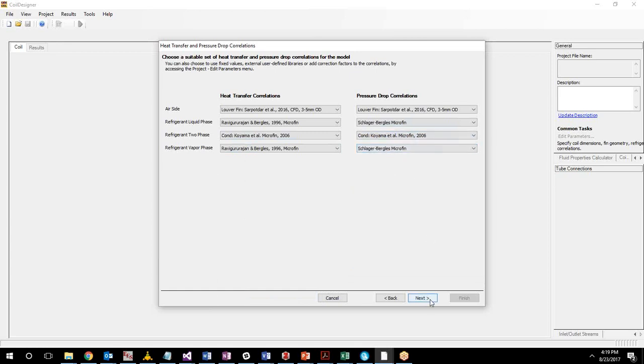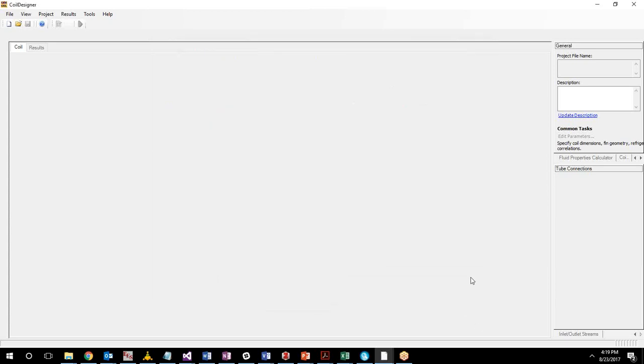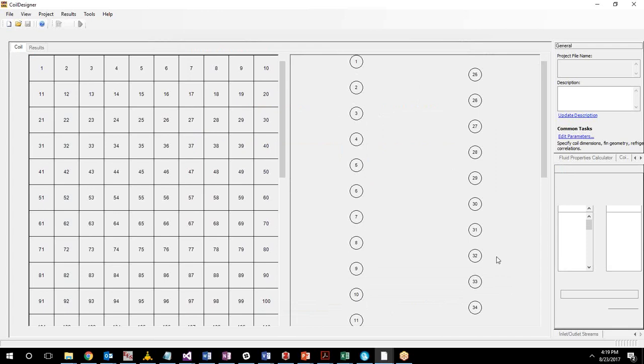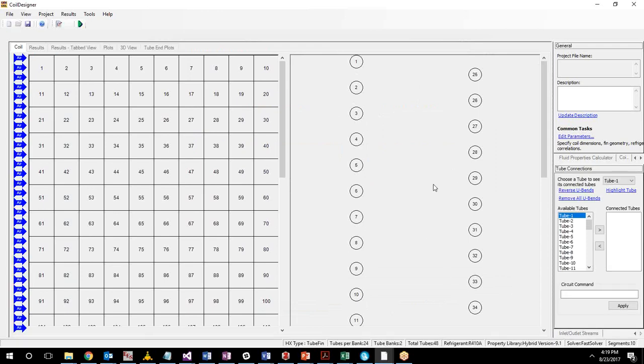And with this, we've set up the fundamentals of this heat exchanger. We've carefully gone through to consider the heat transfer and pressure drop performance for both surfaces. And we now have the framework to perform simulations with this heat exchanger. I should also mention we have the flexibility to add your own correlations, to customize or tune those correlations based on lab data or CFD simulations. If the correlations that exist in the literature that are included aren't applicable for your particular heat exchanger type or aren't matching well with your lab data, there's always room for customization of the tool by each user.